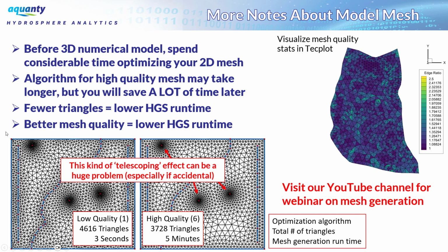On the left, we have a low quality mesh that has about 4,600 triangles, and that optimization algorithm ran in 3 seconds. On the right, we have a higher quality mesh that has almost 900 fewer triangles, and it took 5 minutes to run. So the mesh generation here took an extra 5 minutes, but you've saved yourself from actually having 900 extra triangles in the model mesh itself. And as you add additional layers into the 3D mesh, that could translate into several thousands or tens of thousands of fewer nodes.